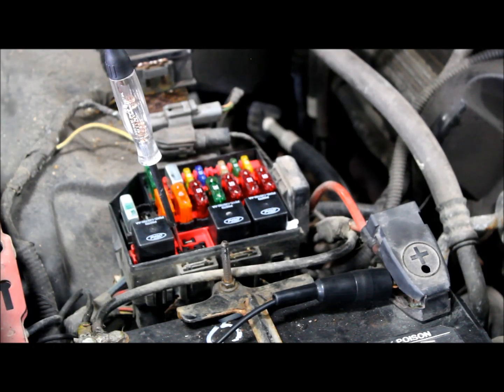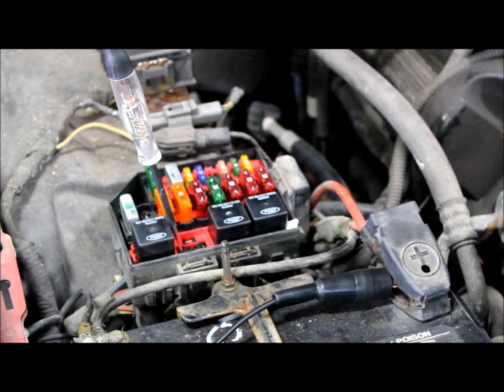Okay, right now I'm hooked to battery positive with my test light. I am in pin 85 on the scan tool, which goes to the PCM. If the PCM creates a ground, that light should light. I have the Autel scan tool hooked up, and I'm going to turn on the cooling fan. Okay, so the light lit, telling me the PCM is capable of creating a ground on that circuit. Now we'll turn it off. Take this out.